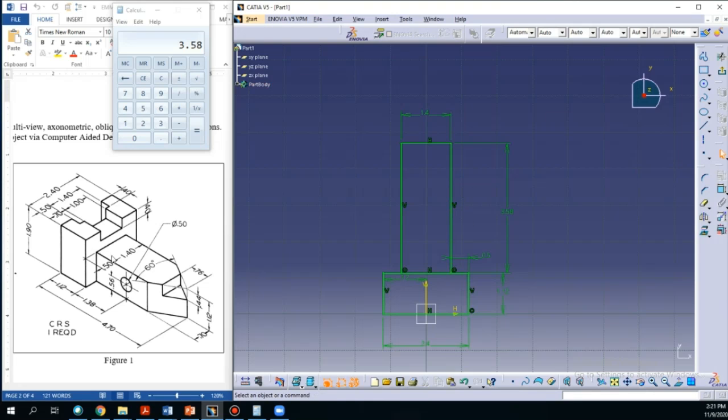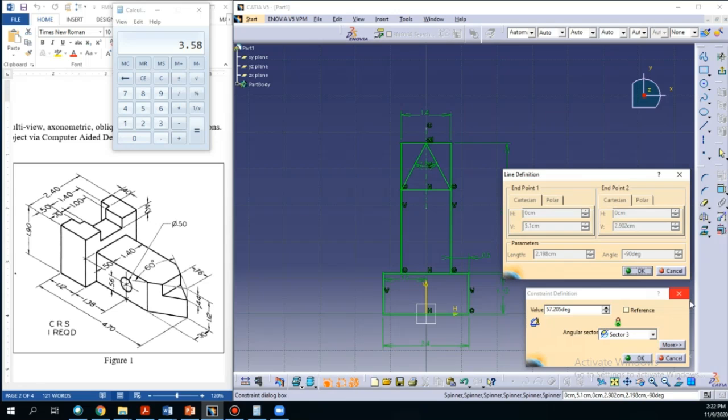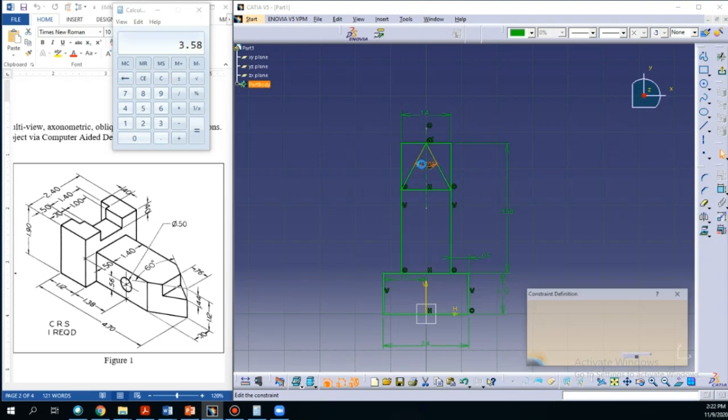Okay, next we can start to draw the top triangle. So we can select the center reference axis. So in this case, this will be 0.7 in the middle. So next we can select the continuous line in order to do the triangle. Select the intersection center, and make a triangle there, then you can select the angle which is expected to be 60 degrees. Okay, do the reselection. So the angle is 60 degrees.